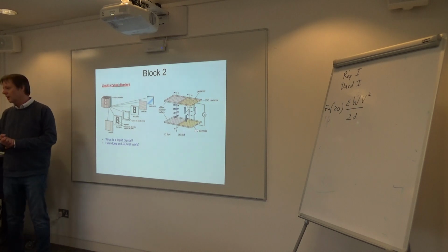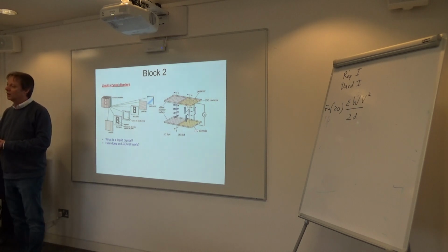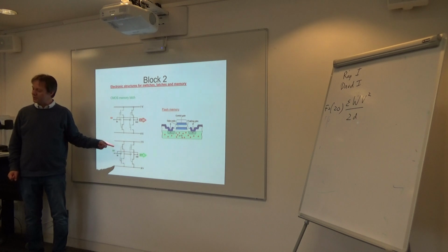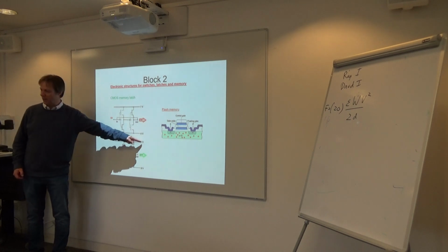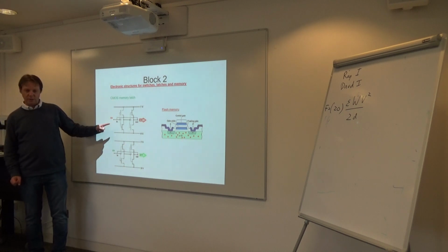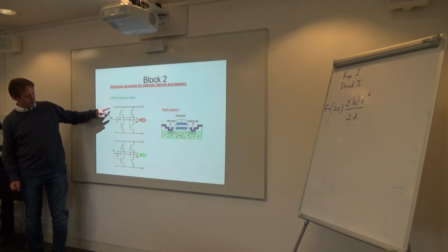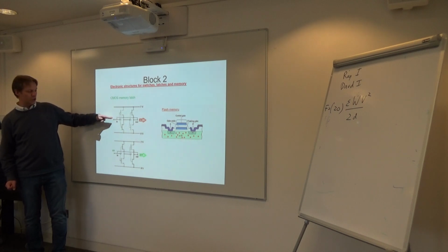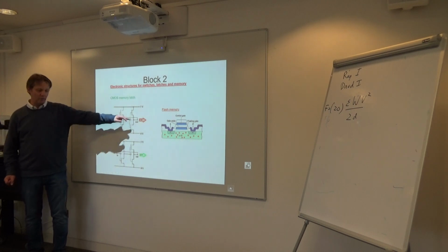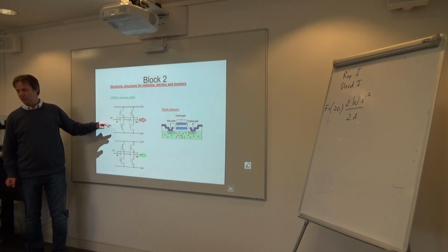Is it worth mentioning that the power required to store the bits comes from the input, so you don't need to keep it powered? That works in the flash device, but it doesn't work in this device. With this device, as soon as you turn that power rail off, everything disappears. Whereas the key thing about this is, if you have a single switch here to switch between, say, 5 volt or 0 volt, as soon as that switches, if that's a push button, you push it to 5 volt, that would remember 5 volt until you next gave it a different input.